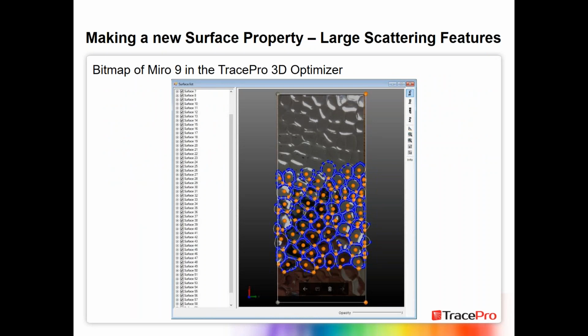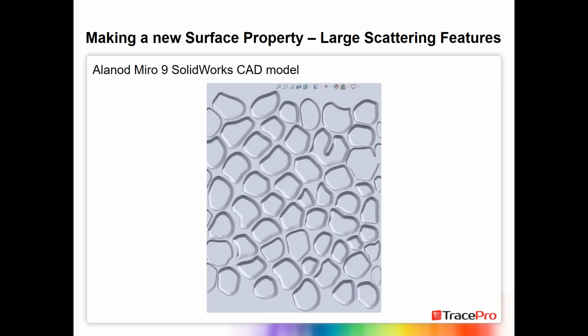So here's a case. I took a picture of the Miro 9, and I opened it up. I added the bitmap of this into the 3D optimizer in TracePro. And the reason I did that is it allowed me to draw these objects here that are representing the features or the dimples on this piece of Miro 9. Now I did a large enough area. I didn't do the entire sample size here, but I did a large enough area to get a representative picture of the pattern.